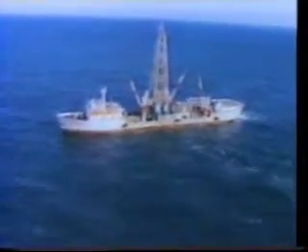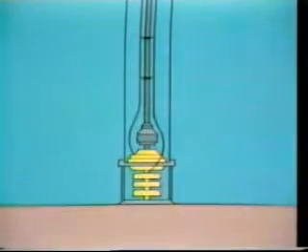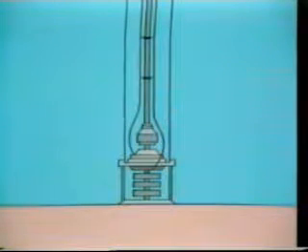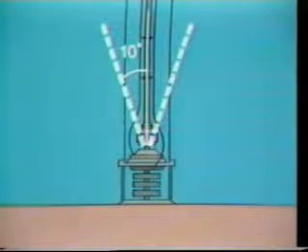Handling the problem of distance from the drill floor to the seafloor involves a system with several very technologically sophisticated components, including the subsea BOP stack, which is lowered down to the seafloor along guidelines and connected to a guide base previously placed on bottom. A flex joint, which is a pressurized ball joint allowing about 10 degrees of angular deviation.